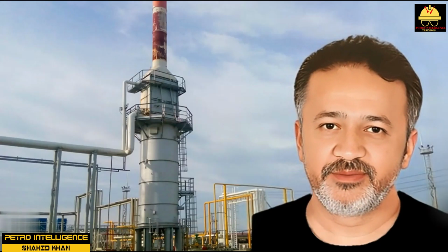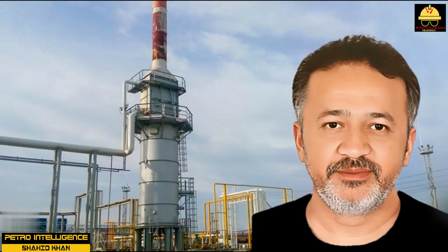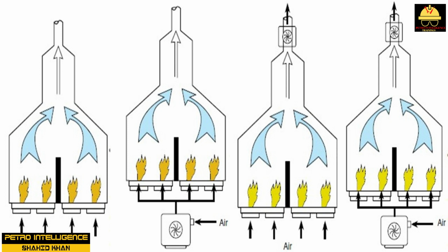Furnace types. Furnaces can be classified by several features: type of draft, number of fireboxes, number of passes, volume occupied by combustion gases, and shape. Draft. Furnace draft can be natural, forced, induced, or balanced. In a natural draft furnace, buoyancy forces induce draft as the hot air rises through the stack and creates a negative pressure inside the firebox. This pressure is lower than normal atmospheric pressure.